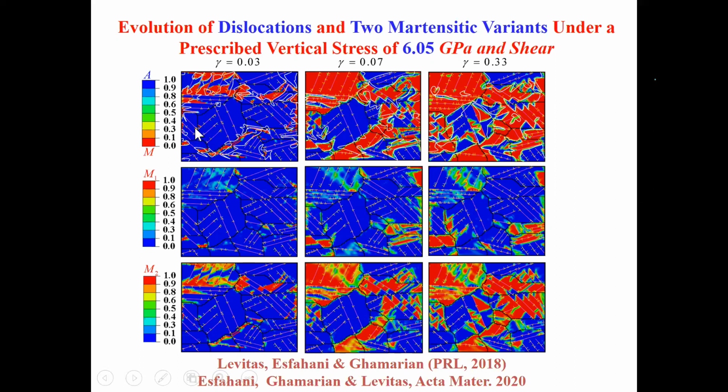And this reproduces continuous distribution of dislocation along slip planes. And it reproduces all required stress concentrators. And also, we were surprised, it reproduces our nanoscale results. But here we can study much larger samples. So this is a polycrystalline sample under shear.